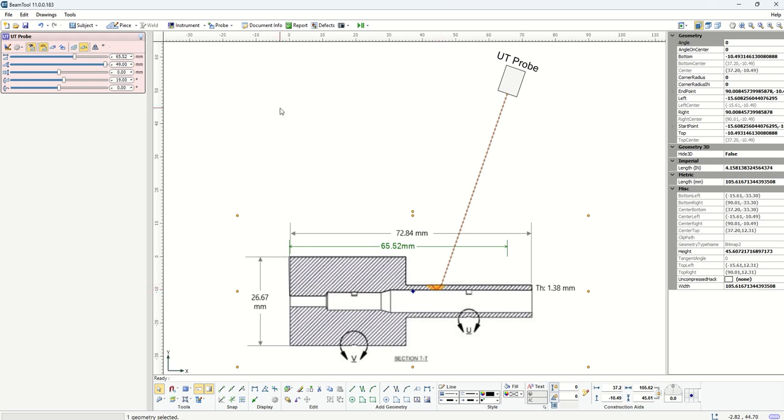At that point, we know that we have a 45-degree shear beam with the near field right on the surface, and then we can design our immersion tank motion to just move axially in this direction, and then rotate the piece at one full travel and be confident that we are creating a technique that is sensitive to finding notch-like or crack-like defects or interruptions in the 3D surface.